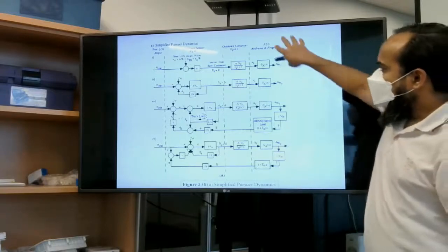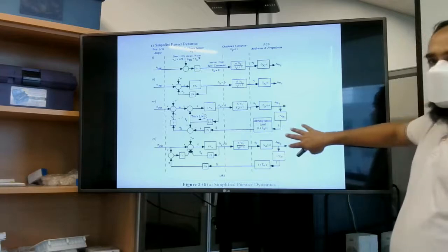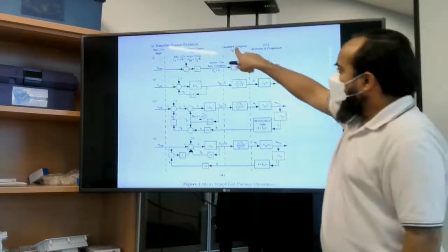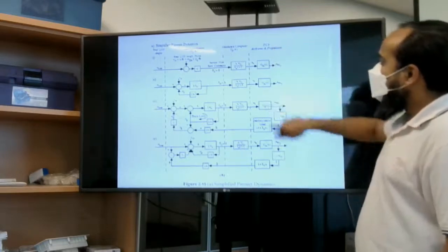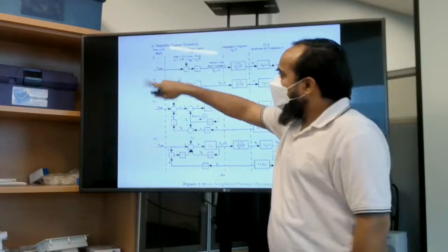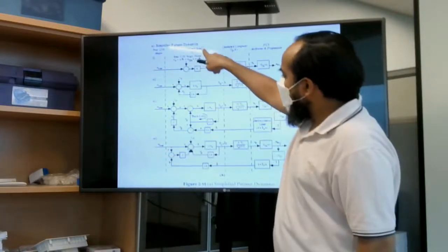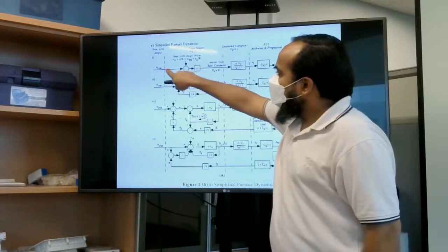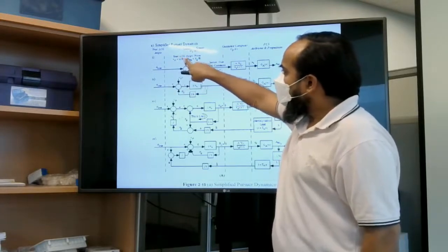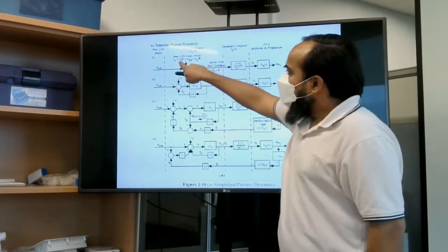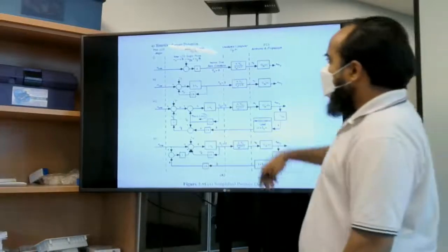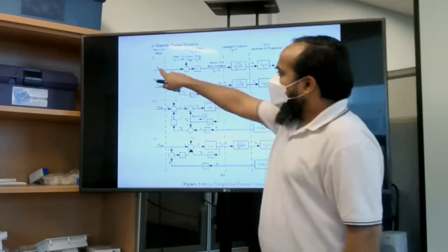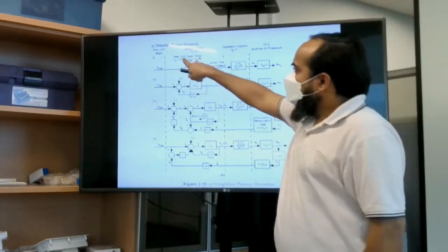Okay, although the perceived diagram is all the same, the simplified seeker dynamics is used for the proportional navigation. So the guidance computer formula is the same and the FCS is the same. Here the line of sight true angle and the guidance sensor, without the radome effect. The guidance sensor receives the true angle and the total line of sight angle noise. We will write the equation for the noise angle in the next slide. So this is the total noise entering the system and the true angle. So our line of sight angle is corrupted with the line of sight angle noise.